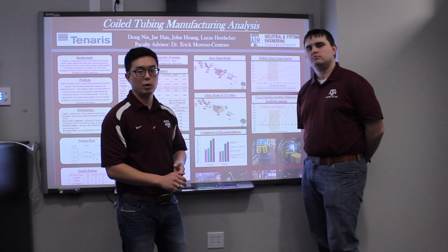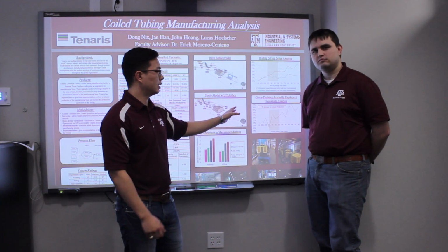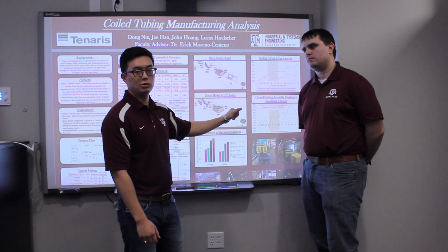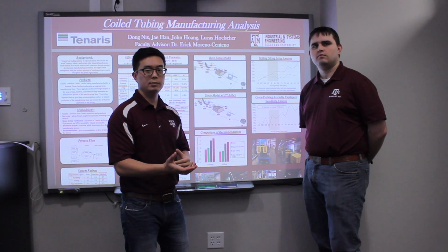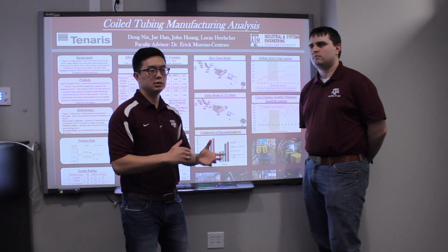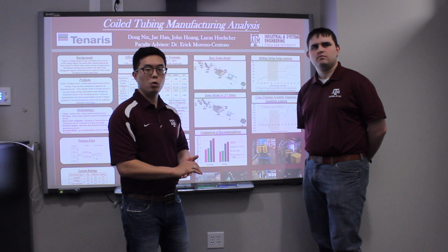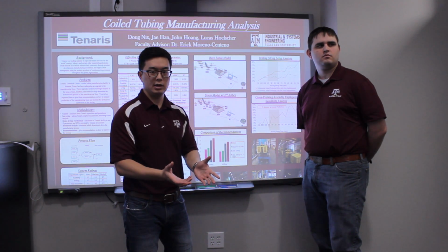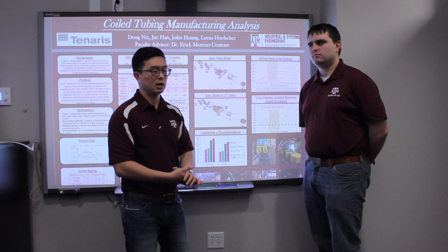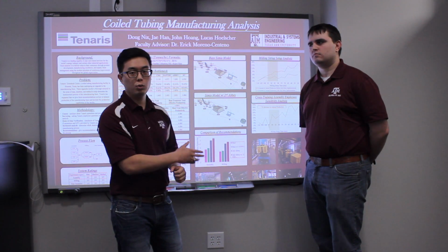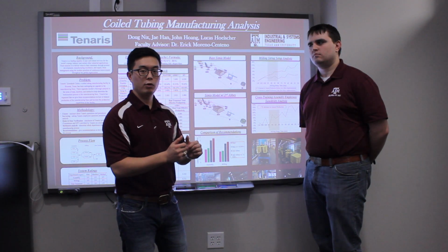Our last recommendation that we will consider is cross-training assembly employees to help reduce the setup time in the milling. Now, the setup for the milling happens around every 2.5 to 3.5 hours. So whenever the setup is needed, one of the assembly lines will be shut down, and their employees will help reduce the setup time. With our Simio model, we decreased the setup time for the sensitivity analysis.